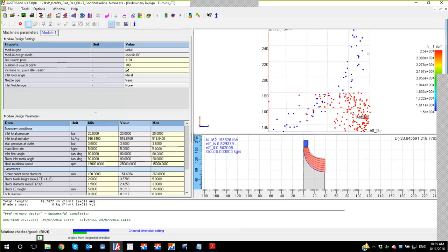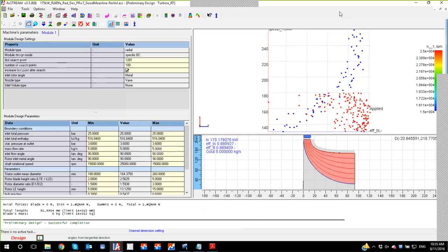So here we're going to reach a maximum around 220 millimeters, and then we can see this is going to drop. So for a particular rotational speed, we're going to have a particular wheel diameter that's going to be optimum. We do go inside the theory of this in the course as well.